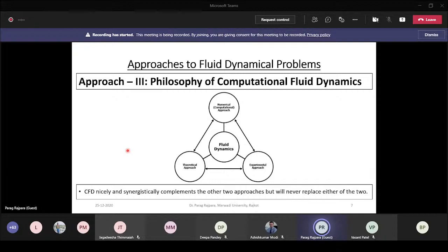That is what we do in CFD. We do not get the solution at all the points in the problem domain. So ultimately, the continuous nature of the solution gets sacrificed. But definitely, the advantage is that you can solve any complex problem and you will get the solution for complex problems.